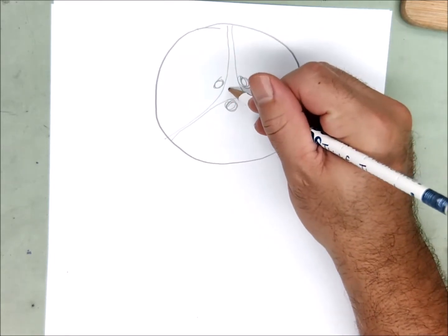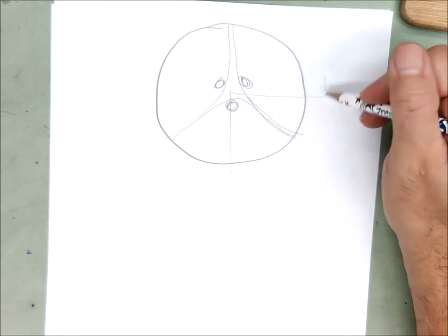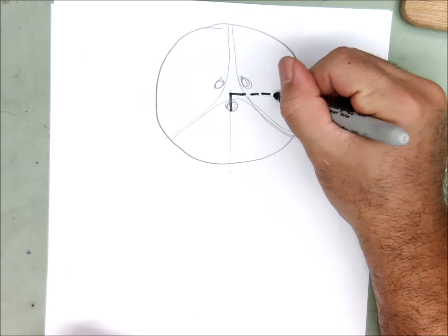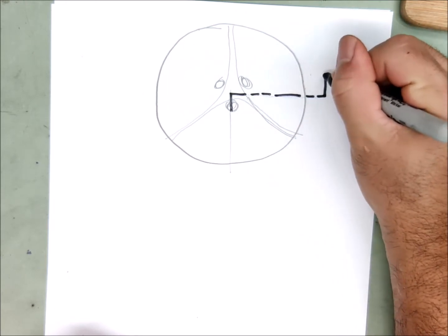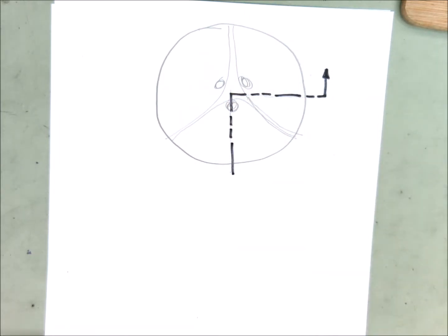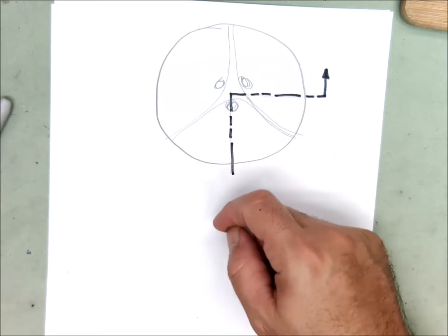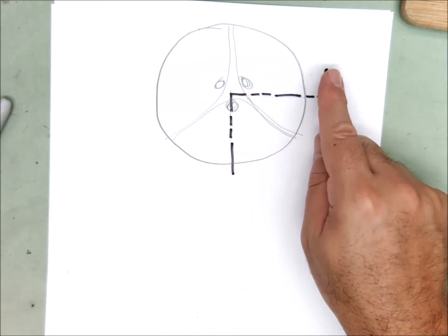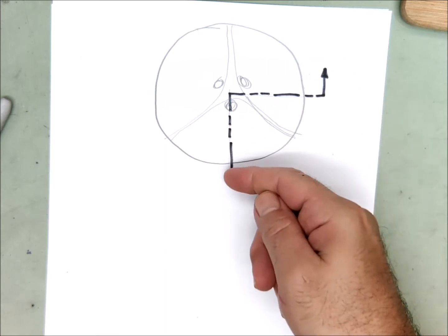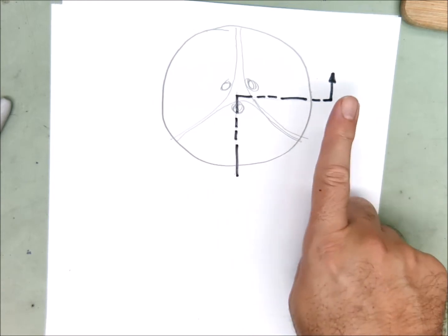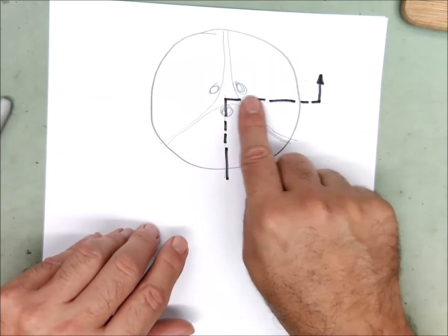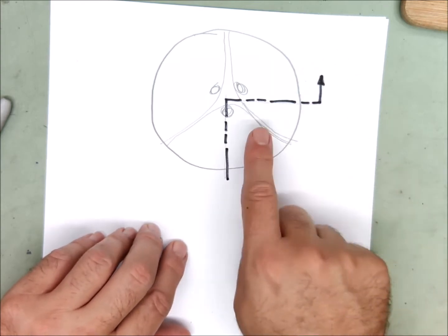What we want to do is set up a section view. And the kind of section that I'm going to call out here is a half section. Try to keep in mind that the half section has an arrow, and it has one arrow because we look in that direction. It's not going to have another arrow pointing down, another arrow pointing left or right. Most of us, our eyes, we all look in one direction at a time. If you have an eye that looks some other way, well, that's okay, but that's not how the section is set up. So only one view direction for our section.